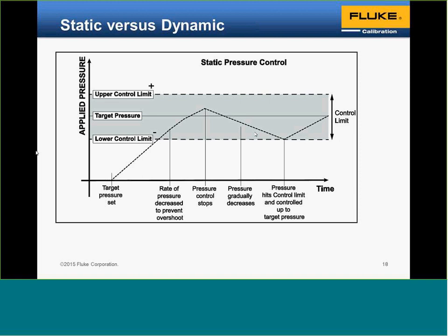The problem is that if you have a leak in your system, all of this goes out the window, and pressure gradually decreases, or pressure increases, which indicates a leak in your system and we're in unstable pressure.